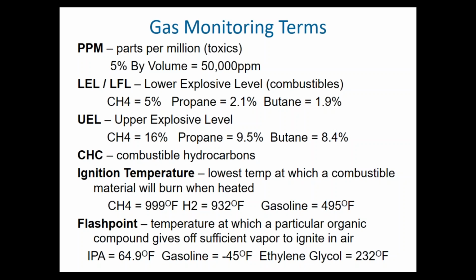And that's why when we sell gas detection, we put it in terms of 0 to 100% LEL, because then one scale on every detector is good for any gas that you want to detect. And all you do is you change your range or resolution to accommodate that particular gas. We'll talk about that when we get into the actual applications.